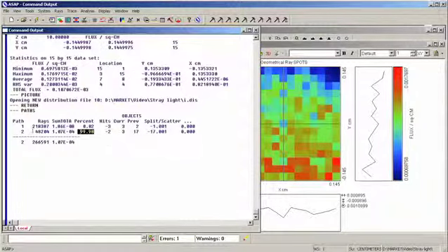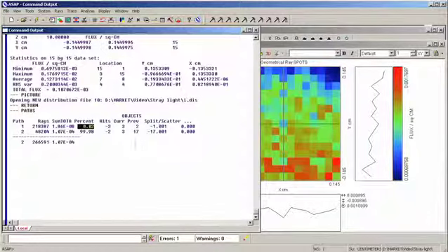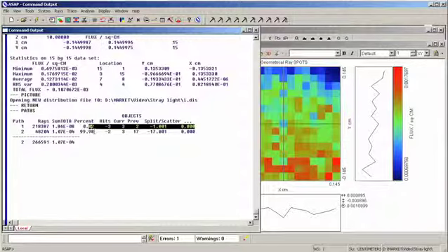So looking at this table, we see that it is scattered from the inner conical baffle, which has over 99% of the stray light, which is the most important path, and that the primary mirror contributes only 0.02% of the total stray light. So if we have a stray light problem, it does no good whatsoever to correct the primary mirror. We have to direct our attention to the inner conical baffle. Otherwise, the stray light will simply not be affected to any significant degree.